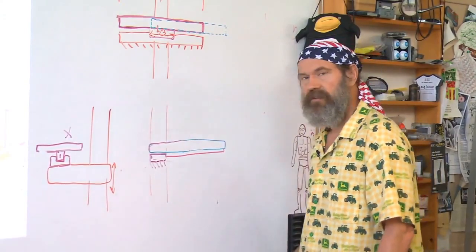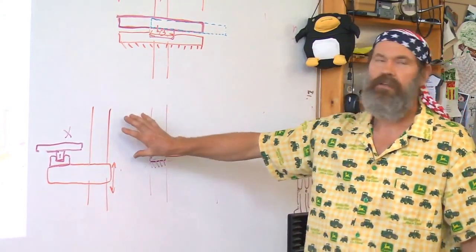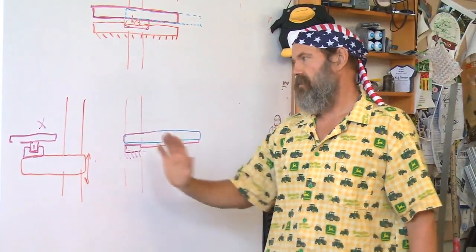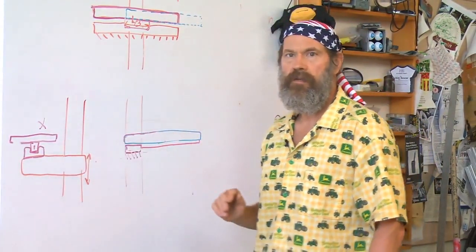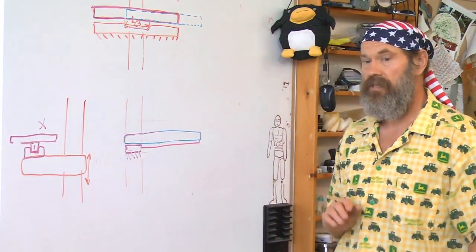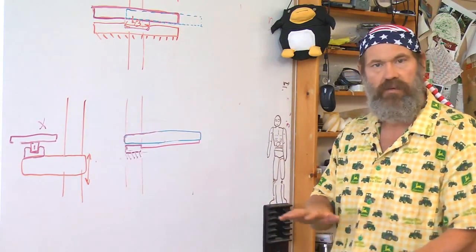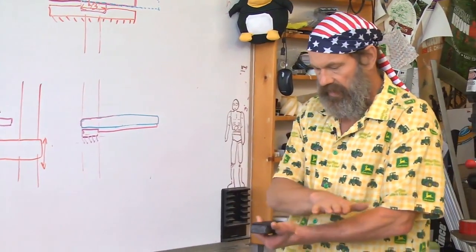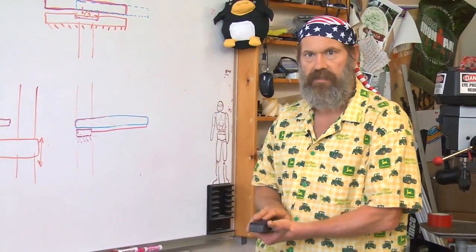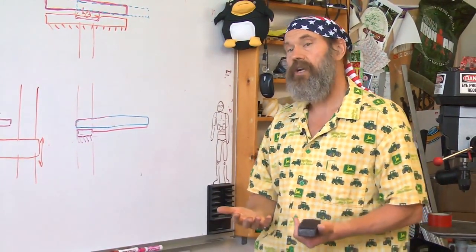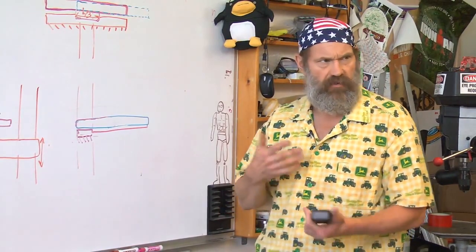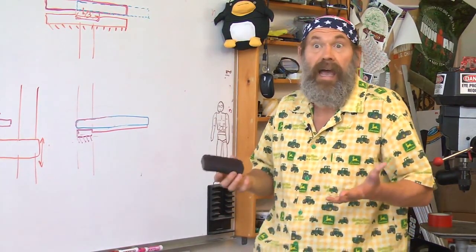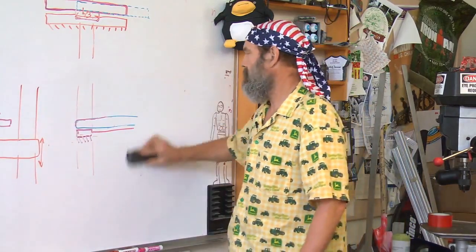Okay, I'll let you guys figure that out. I did the first axis. You guys start to visualize how I would design the y-axis, the in and out one. Is it possible to get those two axes in one bearing block that allows the table to move in x and y very nicely? Can I buy bearings off the shelf that exist to do that? Do I have to invent some kind of a new configuration of bearings? How do you do that?